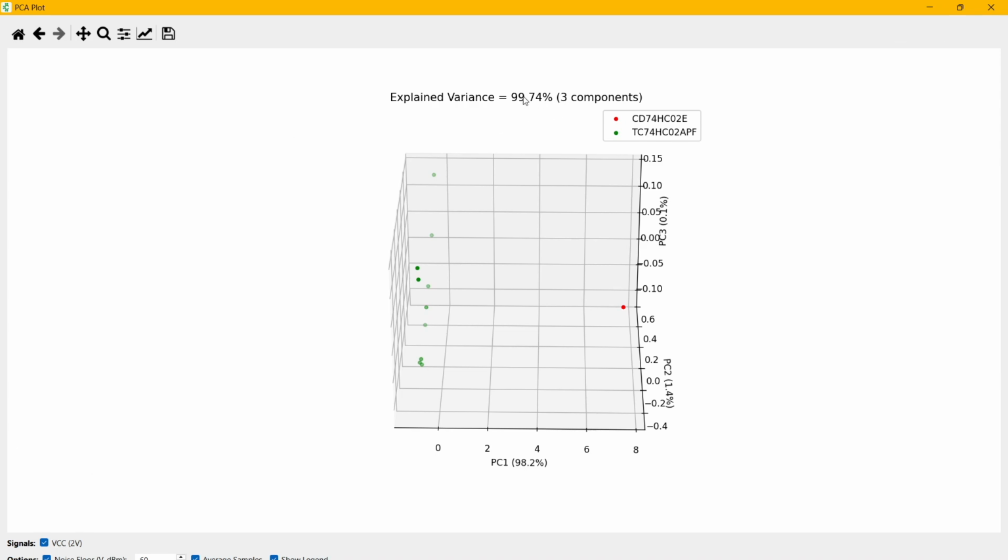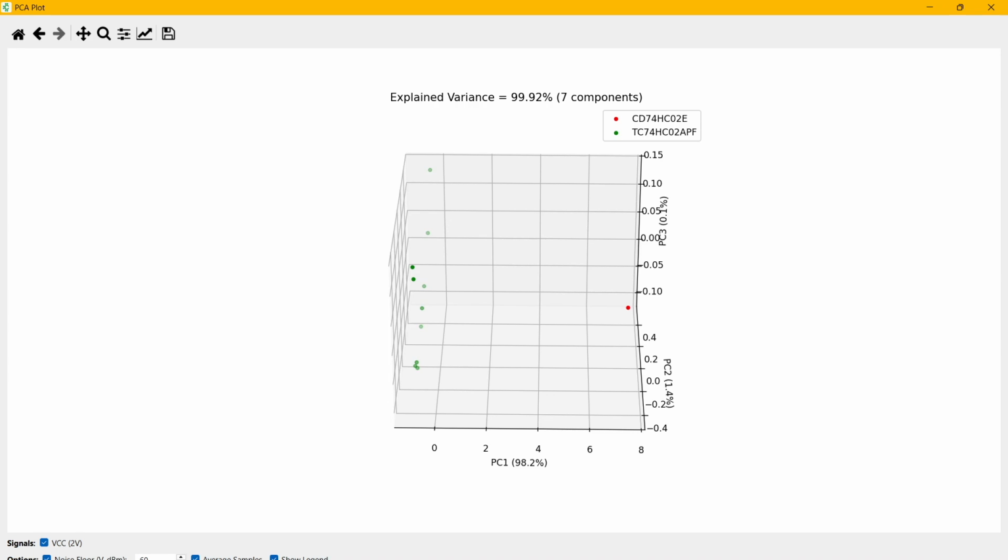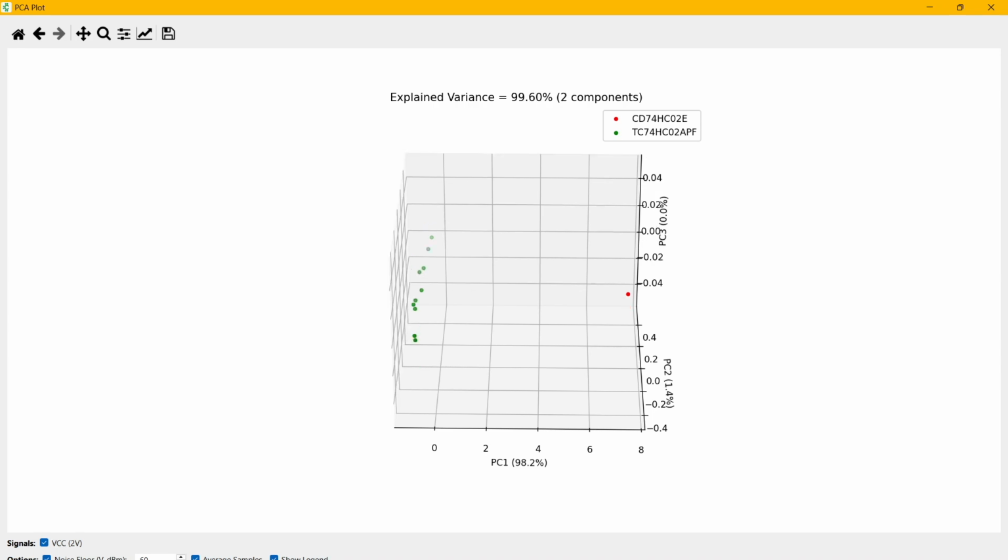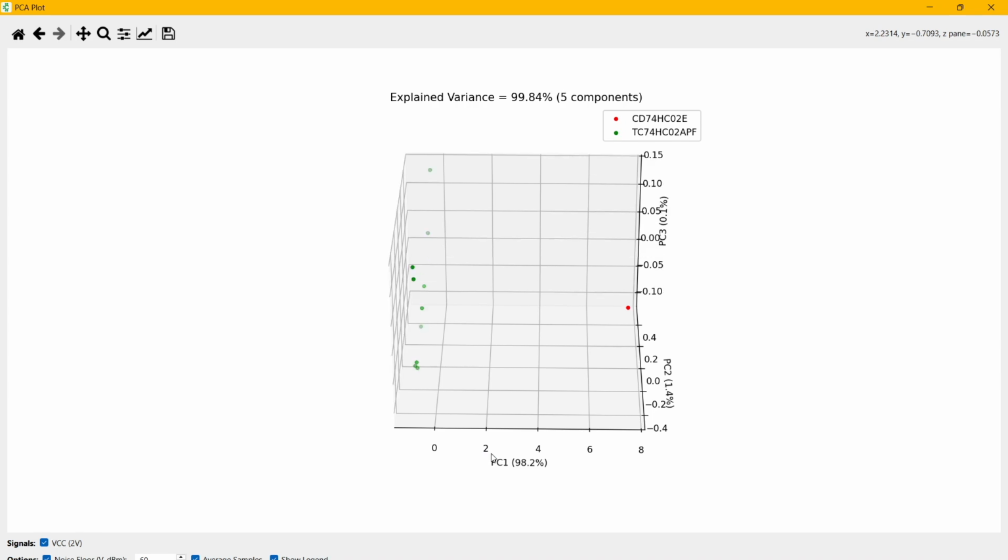Now we can adjust all of these calculations by going down into this bottom selection area, and instead of computing the explained variance for just the 3 primary axes, we can instead select the button to compute the explained variance to reach a certain threshold. In this particular case, I can set the threshold to be something like 99.9 or just 99.5. In both of these cases, the principal component analysis will be run to whatever threshold that's been set. If I set that threshold to be higher, more principal components will need to be included in order to actually reach that explained variance.